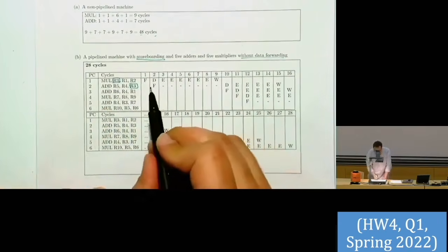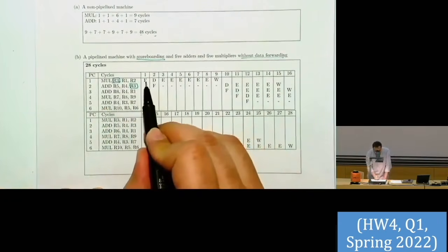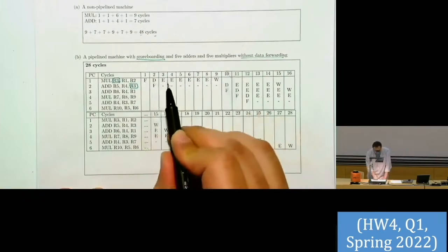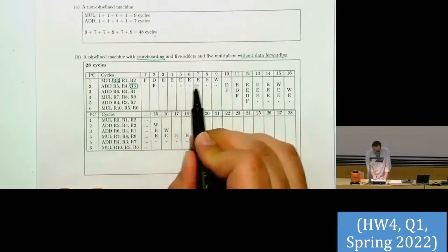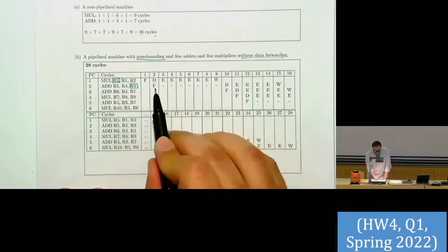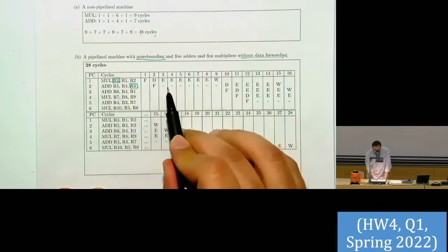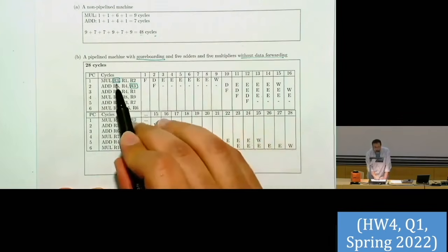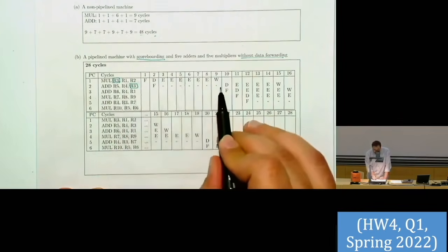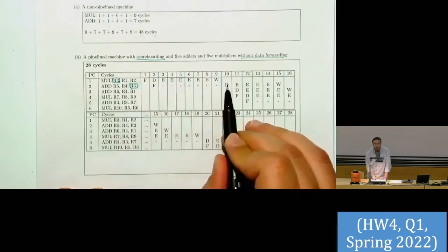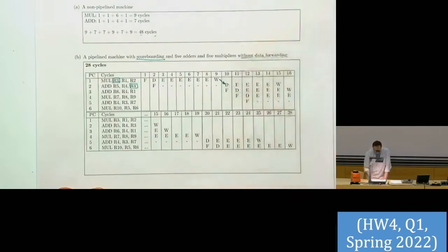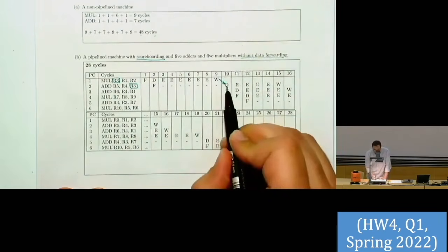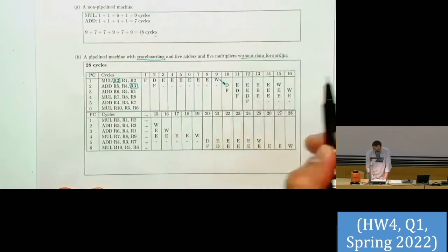The mul gets in, fetch, decode, then 6 cycles of execution, and then writes back. The second instruction is fetched, and then it needs to wait until the result of R3 is written back to the register file to successfully finish decode. After write back, we decode and then continue, right?